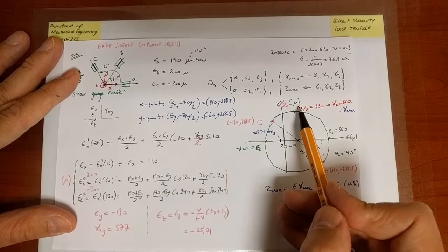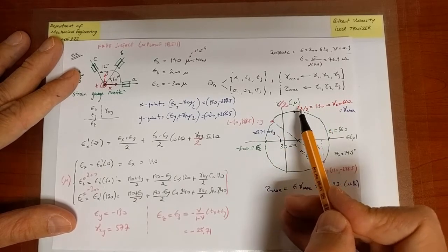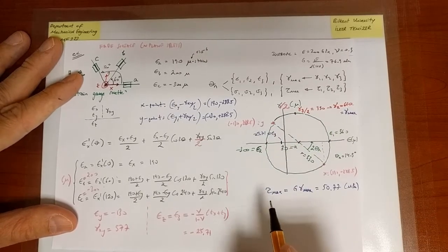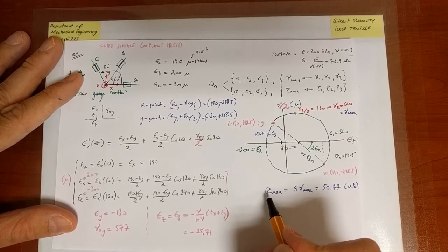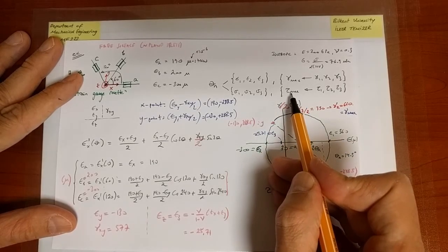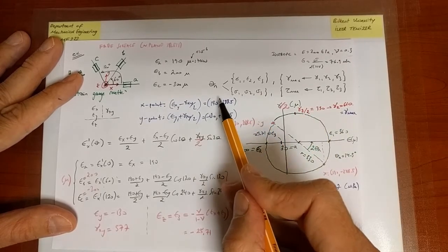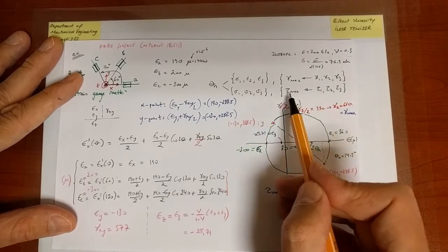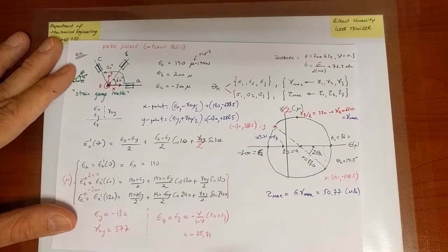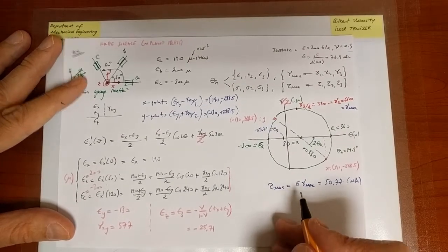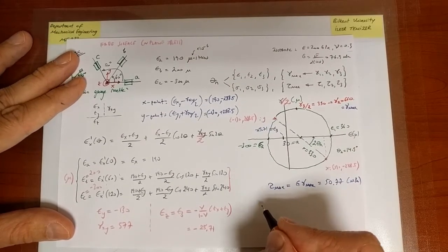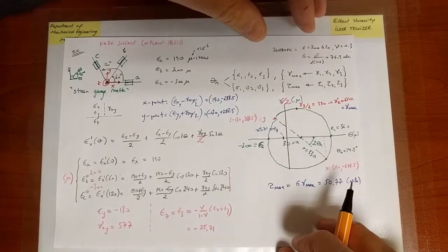Similarly, I could have solved by multiplying gamma 3 with G, which would give me tau 3, and so on for the remaining shear stresses, but here in this case, I was able to directly solve for tau max like that. In general, of course, if you go from the stress state to the principal picture, you calculate these, choose the largest one, but here, that's what I've done. Okay, so then the remaining question is, well, what are the principal stresses?